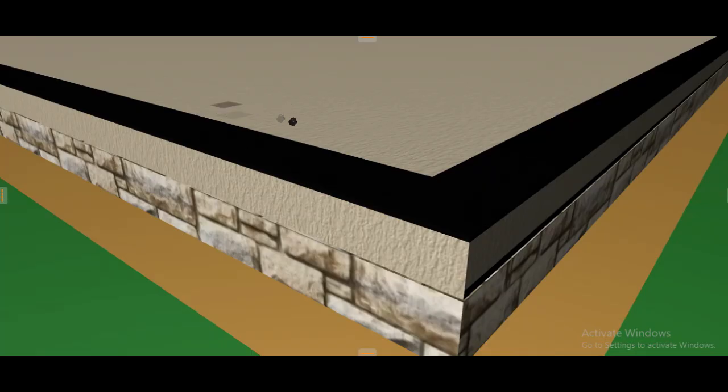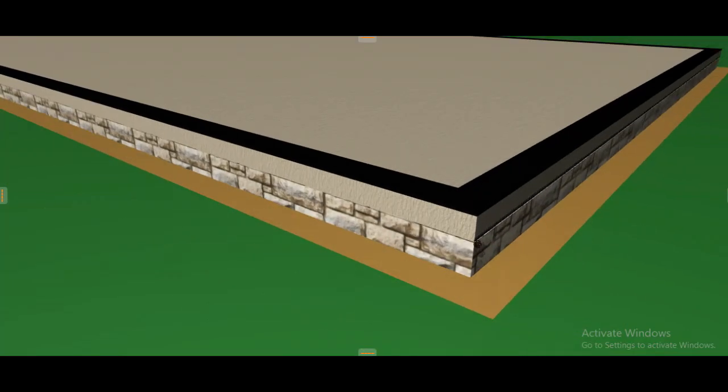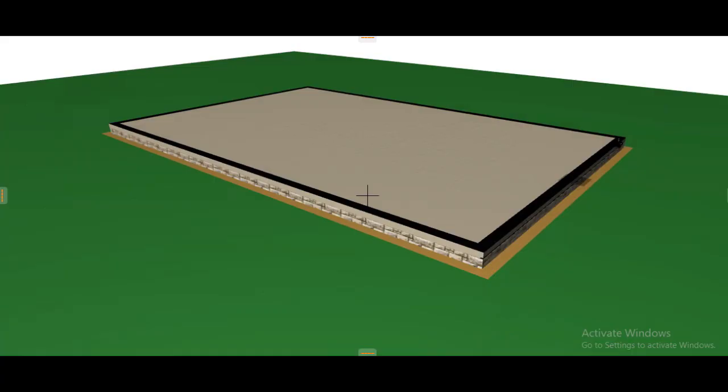But the 200 I'm talking about is across this DPC, and that 200 is the same width as this foundation walling you are seeing here. So the mean girth is starting from this corner, and remember it is the center line, moving to this corner, to this corner, to this corner, and back to this corner. So it is the 39.20 that we entered in the squaring column.